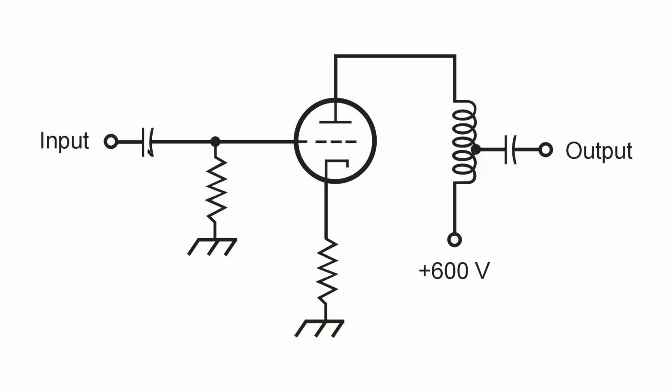This is a radio frequency amplifier. The blocking capacitor keeps the input circuit from disrupting the performance of the vacuum tube, and also keeps the control grid of the vacuum tube from being shorted out to ground, keeps the tube from disrupting the performance of whatever happens to be at the input, probably a radio frequency oscillator or a low-level radio frequency amplifier.